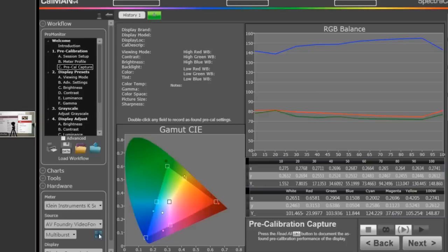But there shouldn't be the banding which is occurring here currently, the jail bar type look. However, that's what we get when the display is slightly overscanned, as many displays are in their default state. And so we're looking for a picture size condition that eliminates that banding.